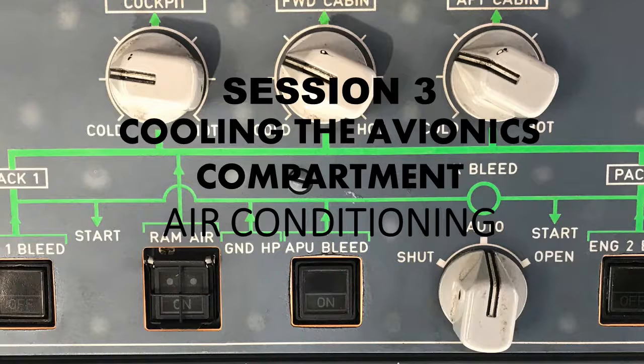Okay, as far as the blower fan's location, that is in the avionics compartment, and you can access that through door 824. Now, what about the extract fan? Extract fan is identical to the blower fan, but I always caution when I share information, always pay attention to the part numbers. Make sure that you're switching exactly what it should be, not just that, gee, they look alike, okay? But do pay attention to part numbers, making sure you're doing the right replacement if you needed to do that. Okay, so there's an extract fan that's also located in there in the avionics compartment.